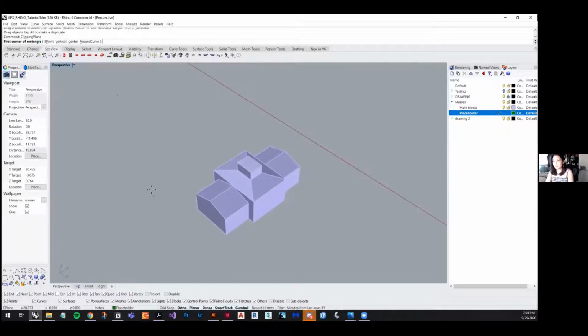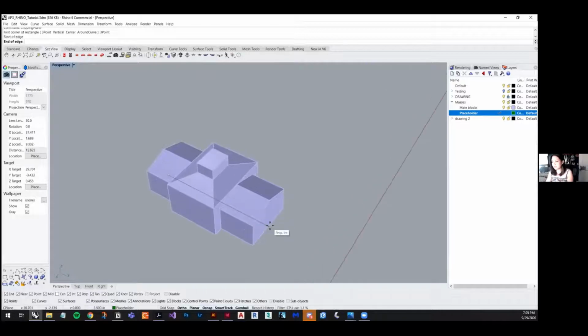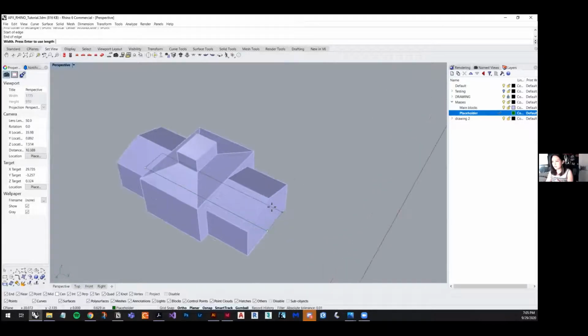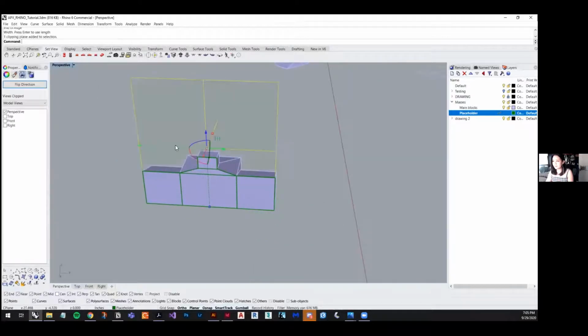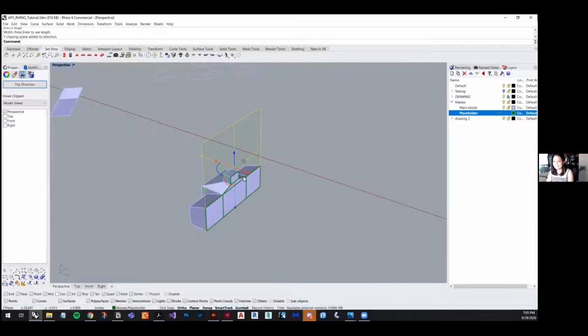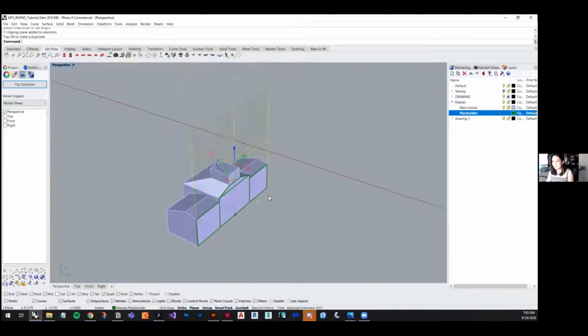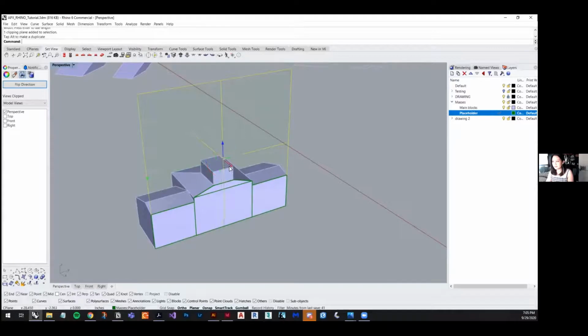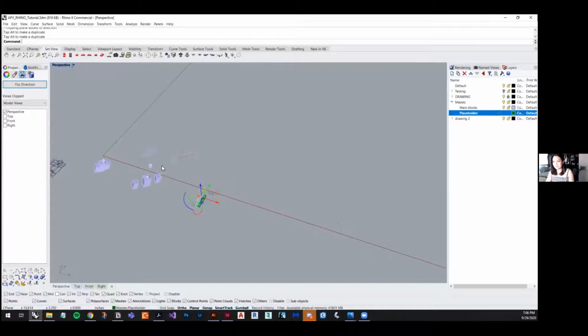When you use clipping plane, what I like to do is do 3 points, because you can always do it in different directions. What if your building is not necessarily in orthogonal view? What clipping plane does is it's a plane that clips, quite literally. It's self-explanatory, and that really helps with any section process. So if this were hollow or some sort, let's hide these so they're not in the way.